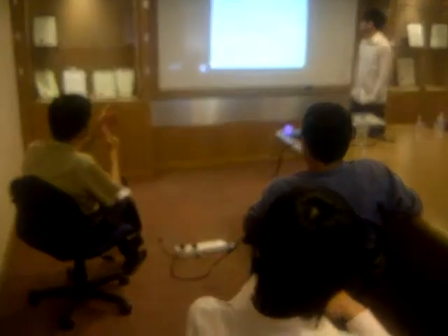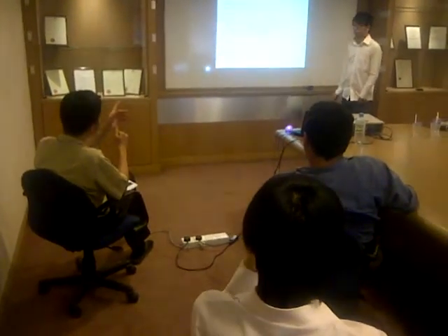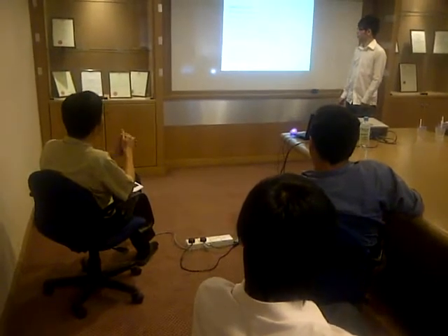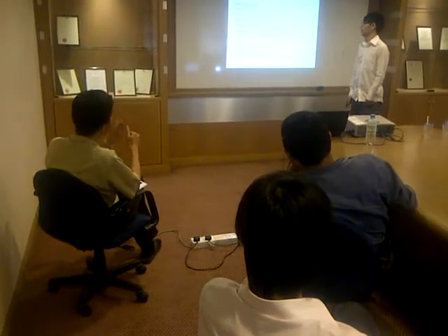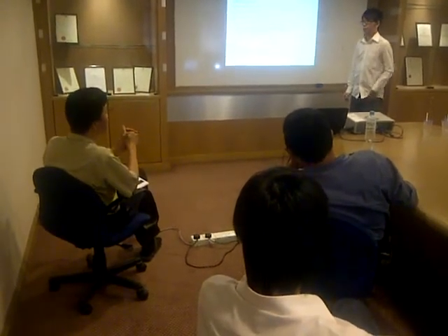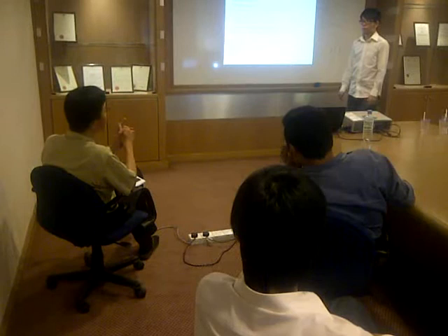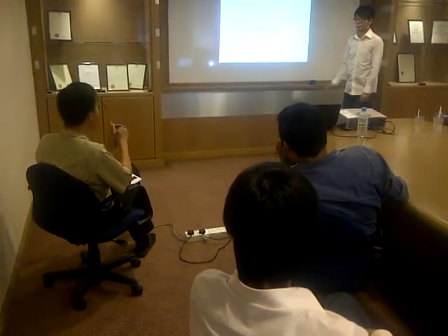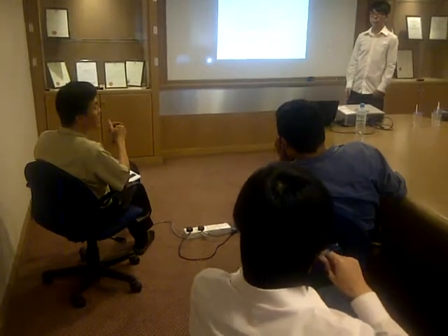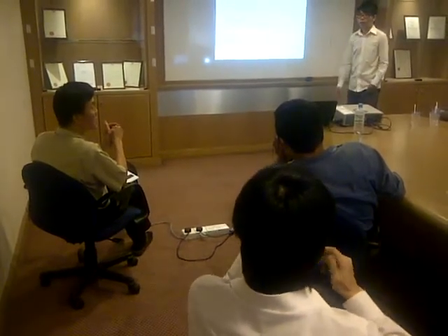So I think the RCD for lighting, normally in the market we use 100 milliamp. Only the switch socket outlet we use 30 milliamp. You know the reason why 30 milliamp for switch socket outlet? Because it prevents the short circuit. Correct, because 50 milliamp can kill a person instantly.